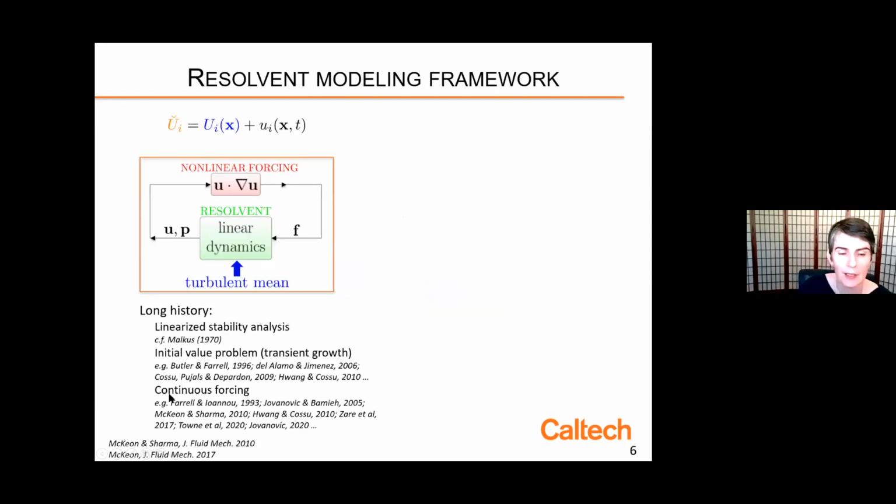So let's get to the meat of the approach. This is an equation-driven method. I want to speak to you about resolvent modeling. Here's a representation up at the top there of what we know as the Reynolds decomposition. If I have an instantaneous field, which should have dependence on space and time, I can divide that into something that is a temporal mean in this instance, and something that has both spatial and temporal dependence, right? So a mean in blue and a fluctuation here in black.